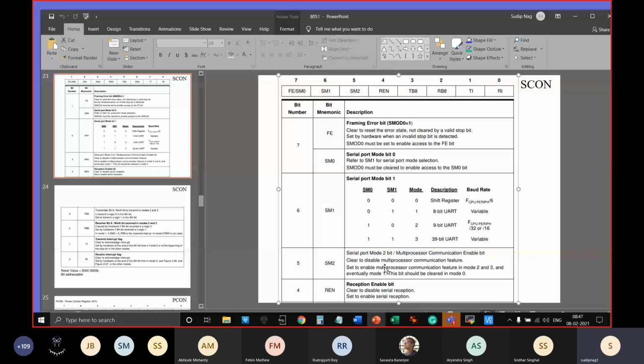where the 9th bit can be used as address, or you can have more microcontrollers where more serially transmitted address bits are available, and we can discuss this in a later part because I'll first complete the serial UART, but this is actually very important and very simple also. The only thing is that apart from data, you have some address information along with your data within a given frame. That is the basic idea behind having more bits than 8.